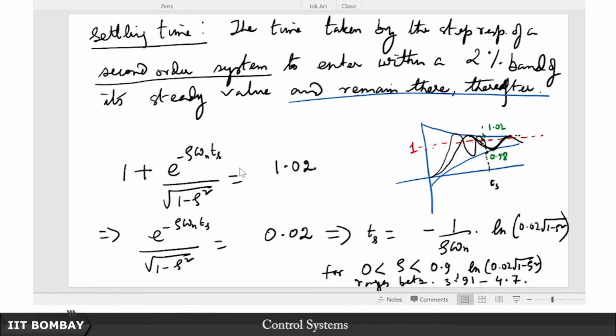On the other hand, the settling time gives you another measure of the speed of response. What is that? This is telling you how soon you basically settle down, so how soon your transient oscillations decay to insignificance. So although these are both telling you how fast your system responds, they are basically two different notions of how fast a system responds. I want you to bear that in mind. So do not make the mistake of thinking that rise time and settling time have the same connotation.